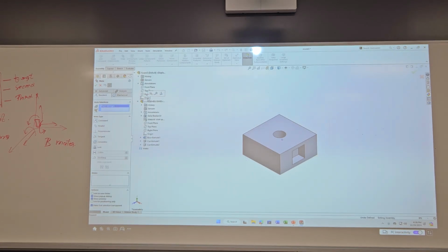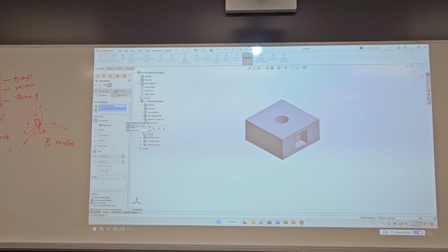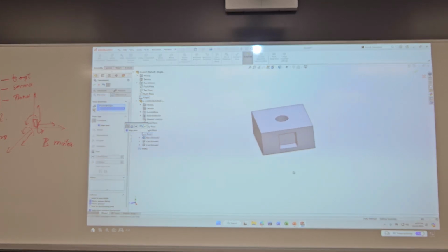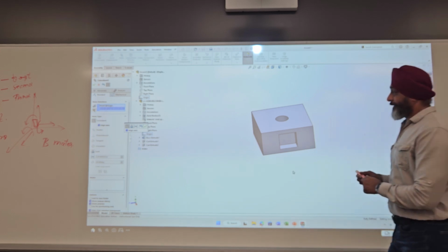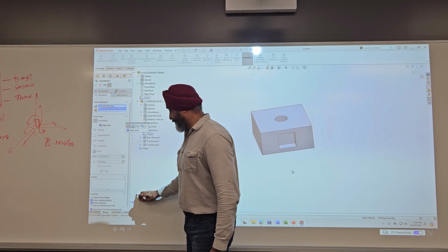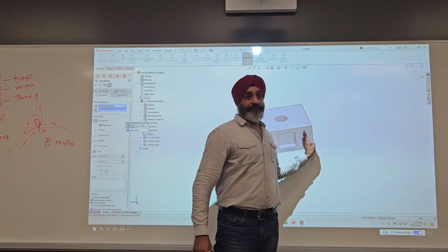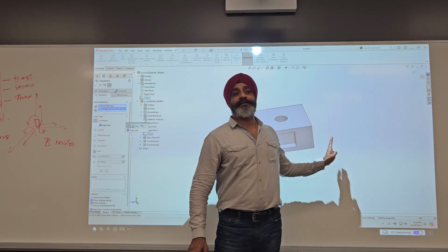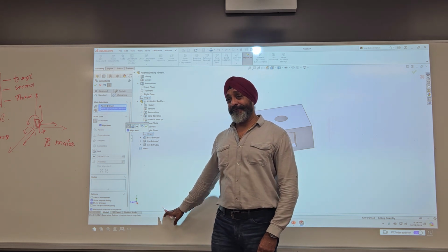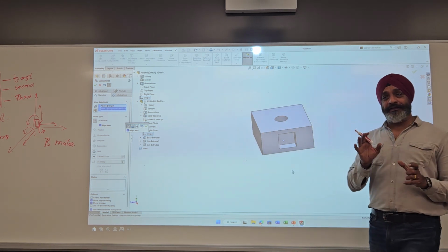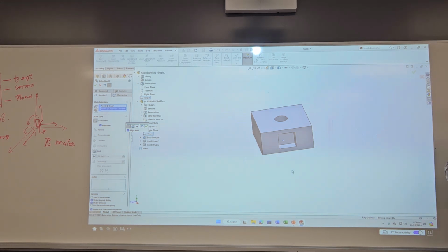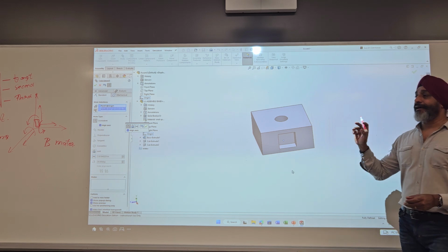Okay, let's see origin to origin, what it does. Because the origin is right in the center, and the assembly origin is there. So if we do that, there are two things, align axes or not. What that means is, when I say align axis, the Y of the assembly will align with the Y of the part. X of the assembly will align with the X of the part, and so will the Z. Okay, if I do not want the axis to be aligned, I just want it aligned with the origin, which means I still want to move it, then I will uncheck that box here.